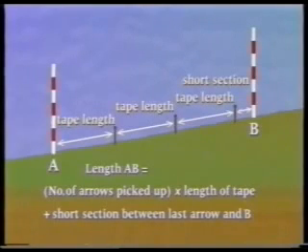As a check, the line should now be measured again, this time starting at B and ending at A. The two measures should agree very closely. For example, over a constant slope of 100 meters, using a 30-meter synthetic tape, the difference between the two values should be within 50 millimeters. And using a 30-meter steel tape, agreement should be better than 10 millimeters.